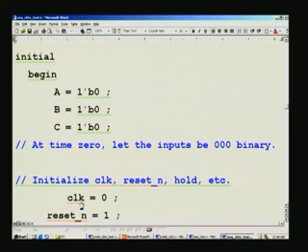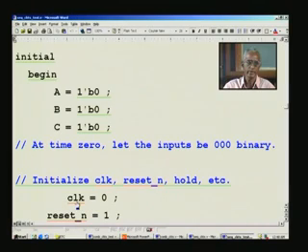We have not covered this as such. Clock, we said, is what we are going to generate, and we saw that earlier, having defined clock divided by 2 or something like that and equating it to 10. What it means is the clock half time, not the time period but half the time period, is 10 nanosecond, if you had declared the time base as 1 nanosecond.